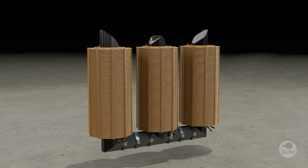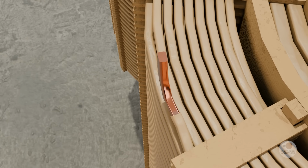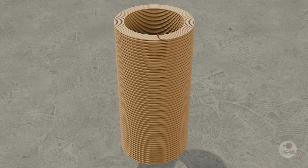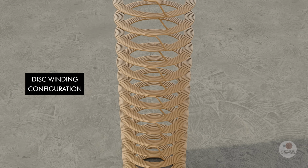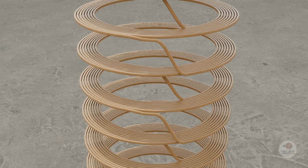The high voltage winding uses thinner conductor since it carries lower current, but it must withstand extremely high voltage. To manage this high voltage, engineers employ a disc winding technique, which provides excellent insulation control and distributes voltage stresses evenly across the winding.